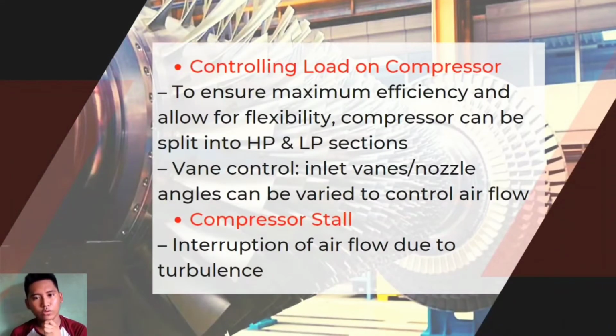Controlling load on compressor. To ensure maximum efficiency and allow for flexibility, the compressor can be split into high pressure and low pressure sections. Vane control: in inlet vanes or nozzle, angles can be varied to control airflow. Compressor stall: the interruption of airflow due to turbulence.